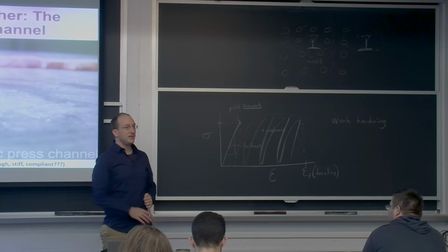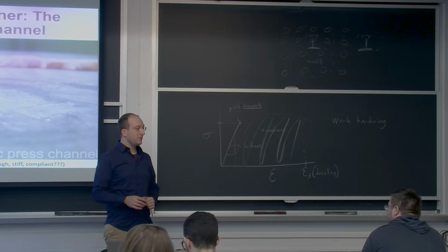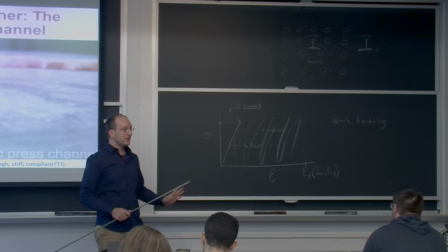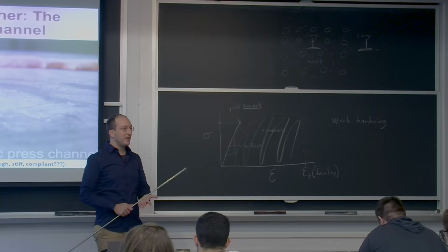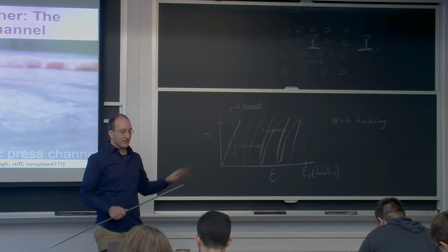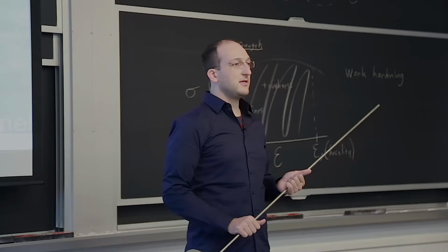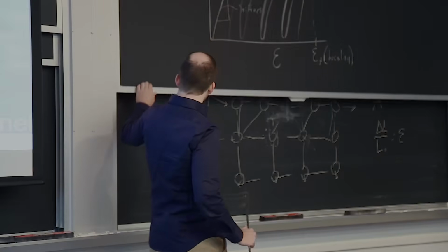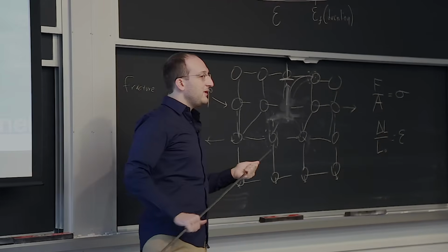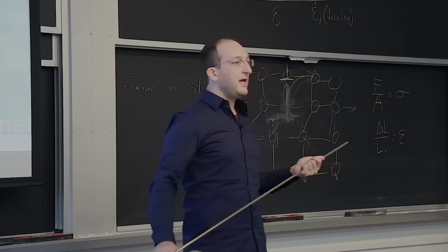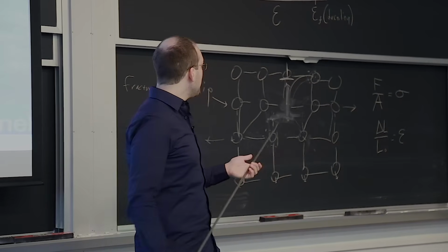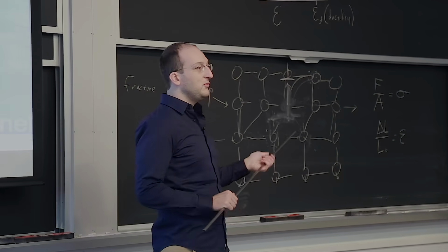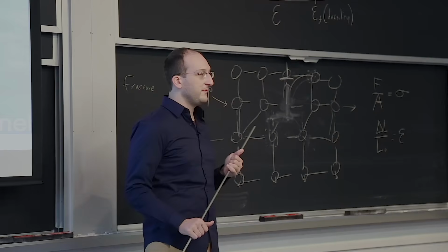So the reason something would be ductile versus brittle is whether or not you can plastically deform it. And that means whether or not it's more energetically favorable for dislocations to keep moving versus just breaking a plane of atoms in any irregular direction and causing fracture. So again, ductility versus embrittlement is the interplay between slip and fracture. Slip is normally done by dislocation movement. Any defects created by anything, especially radiation damage, will make slip harder so that any continued energy you put in will not move dislocations but move towards fracture.